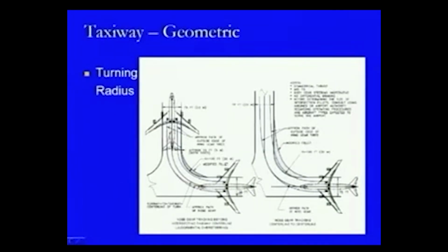So, the axis of the aircraft is just superimposing on the center line of the runway strip, and then as this connectivity is being provided, we have this center line like this. So, this is the center line of the curve, and this is the position which is taken by the aircraft after taking the turn on the taxiway, and again it is aligned with the center line on this taxiway with the wings coming out in the safety area.